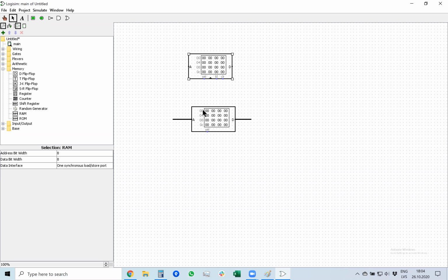For random access memory, you see there is address, there is data, which is data in and out. Select signal selects between data active and inactive. This load is the output enable signal basically, and for this clock signal, its description says memory value updates on rise from 0 to 1.